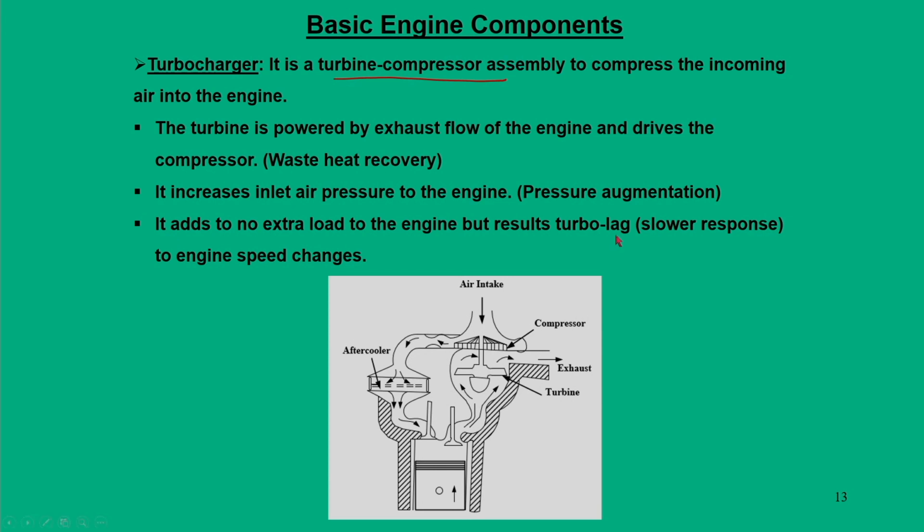But when we run these turbocharged engines, there is a kind of lag. When the user changes the engine speed, there is a lag, what we call turbo lag or slower response. It adds pressure augmentation, but at a relatively slower response.